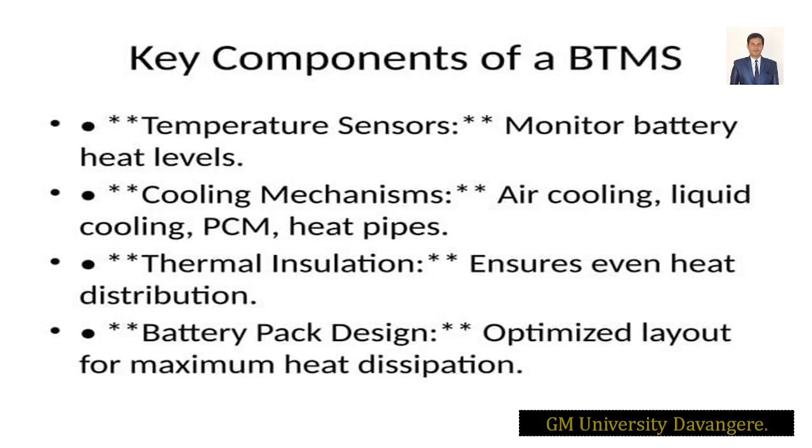So the temperature sensor will sense and monitor the cells' and cooling temperature. Every 100 seconds, it will give the data. What is the purpose of needing this? You have to see the difference between two cells, how much temperature is there. If one cell is giving 45 degrees, another is giving around 10 degrees centigrade, and another cell is giving around 25 degrees, then we have to see why it is giving that much temperature. What are we going to monitor? What action are we going to take? So that is the purpose.